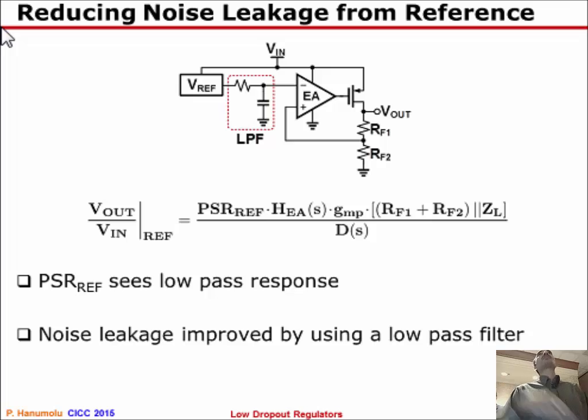The simpler question boils down to how one can design the error amplifier efficiently. There are many ways to design this error amplifier with nanoamps of bias current. And since the bandwidths are not important in the applications you are referring to, the quiescent current can be tens of nanoamps if you are only supplying a few tens of microamps of load current.